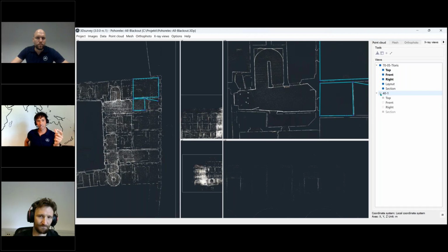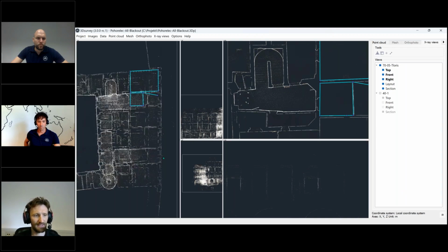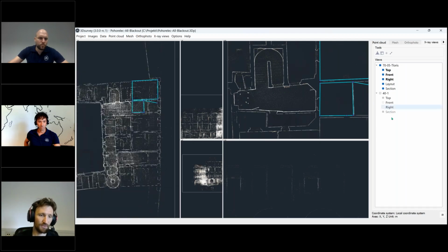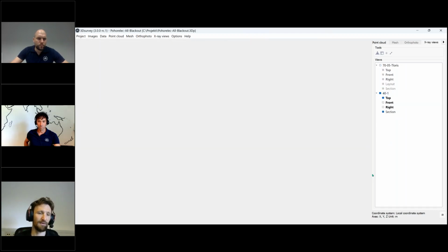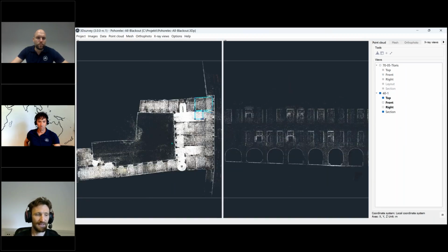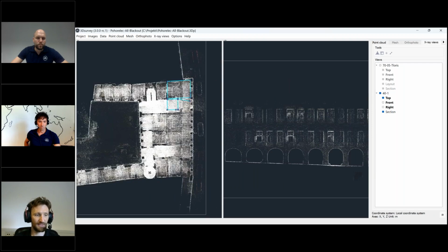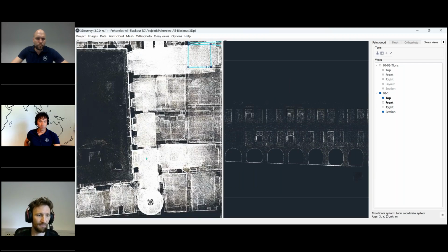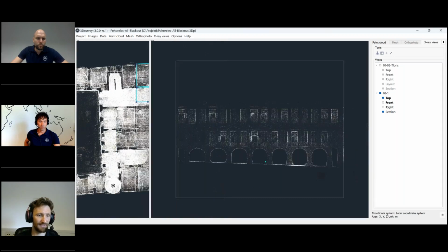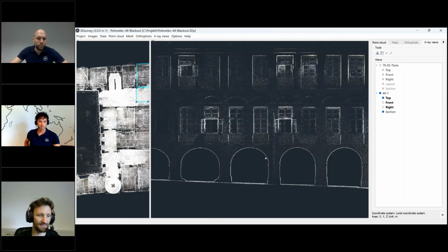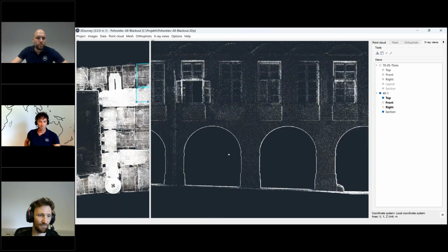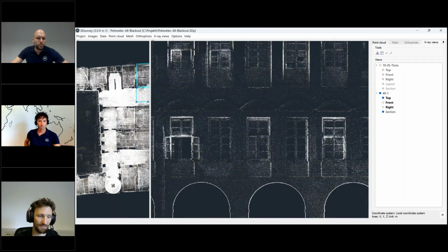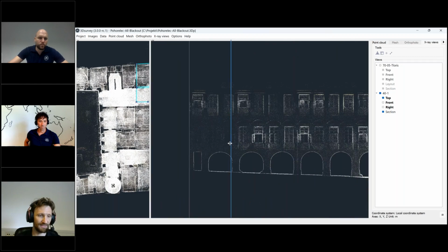It's probably connected with the density of the point cloud. Exactly. Because it's not so dense on the outside, we got a sparse point cloud and weak lines. For those cases, I tried transparency of 40, which gave me an oversaturated image on the interior. But I repeated this step on the facade, and it gave me very nicely defined arcs and windows. This made vectorization much easier.